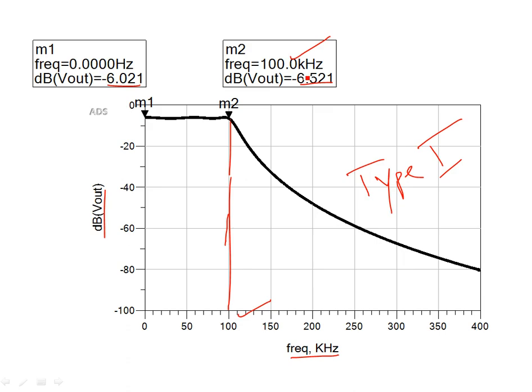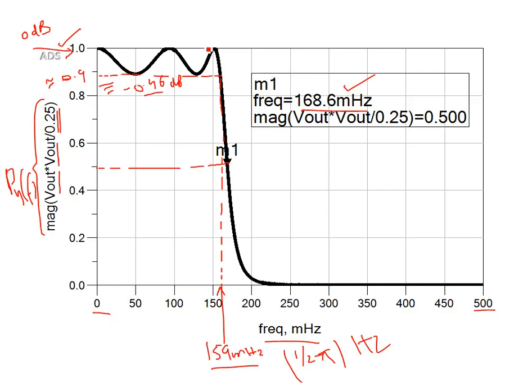You have to start with the prototype low pass filter. This is a prototype low pass filter. Now this has the last n dB ripple occurring at 1/2 pi hertz, which defines the pass band edge of a normalized low pass filter. This can be denormalized by dividing the reactances by whatever is the desired pass band edge frequency. And you have to scale the reactances by the same factor by which the load and the source impedance have been scaled.